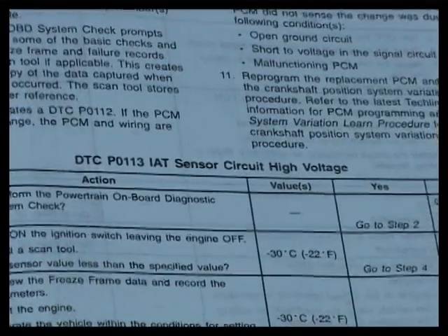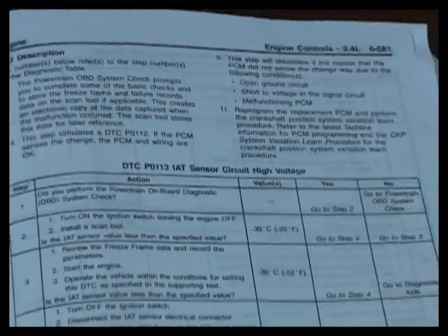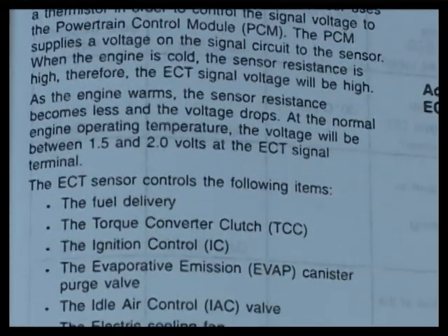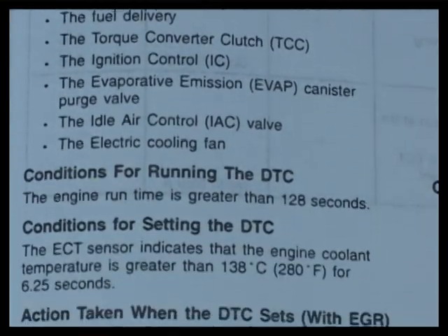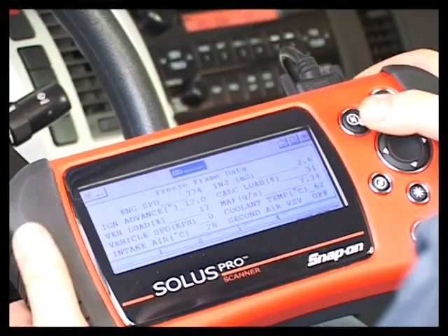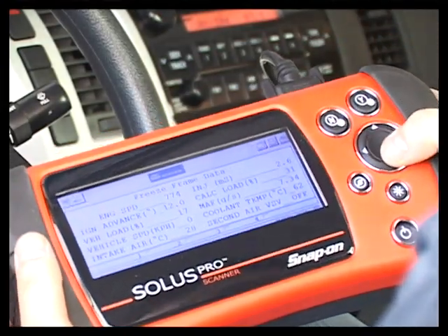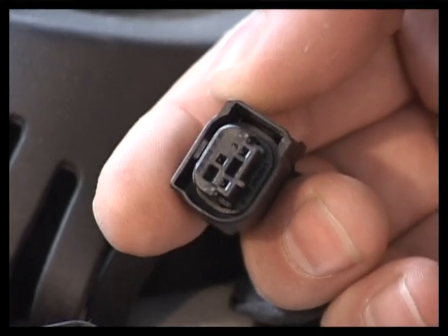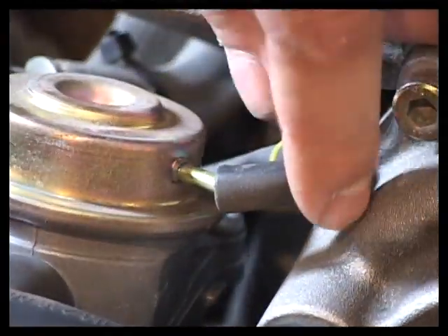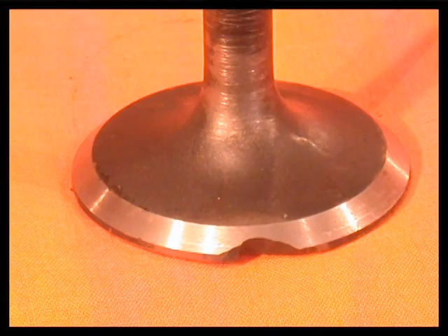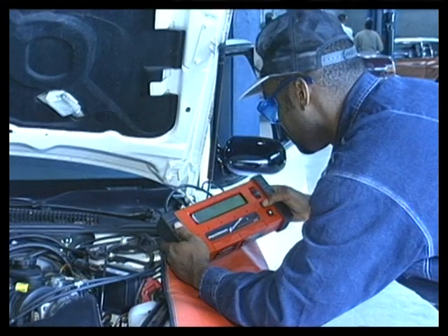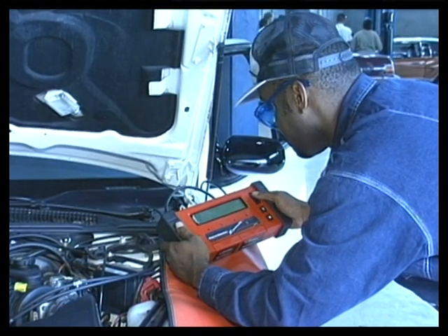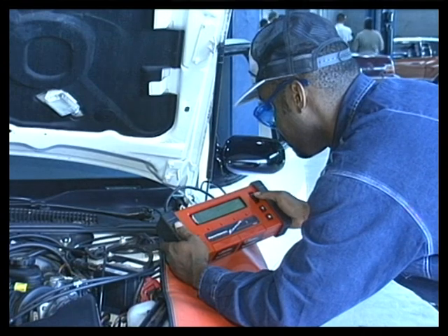Always refer to the service manual for detailed instructions for using onboard diagnostics. Procedures vary even with OBD2 standardization. In ending, remember, many problems that affect a computer system are conventional: loose wire, corroded electrical connection, leaking vacuum hose, fouled spark plug, or burned engine valve. For this reason, always check for the most common types of problems before analyzing more complex computer-controlled components.